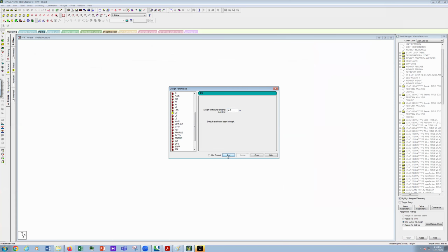So this LX, LY, and LZ we are assigning for the rafter. We don't have to assign for the column because the column is not broken, but the rafter is broken at multiple spacing. Again, we go to our next item.